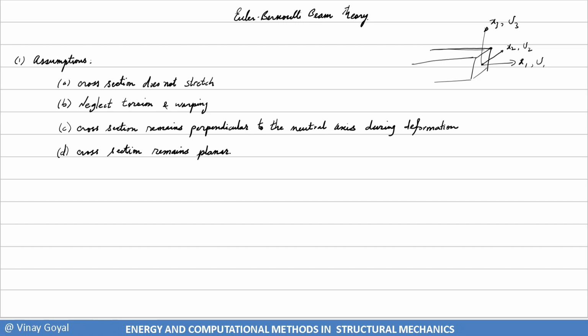Okay, so the next step is to really understand what the displacement assumptions are. We start with U1, which is the axial direction of this beam, or longitudinal direction. And we're going to say that's equal to small u1, only a function of x1. And I'll explain physically what's going on, plus x3 times beta, plus x2 times beta.